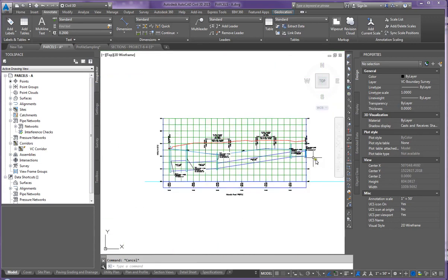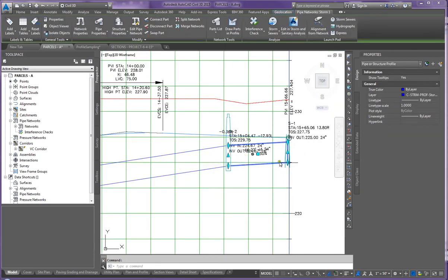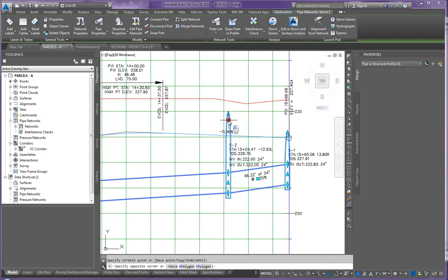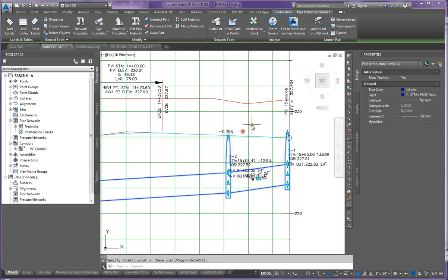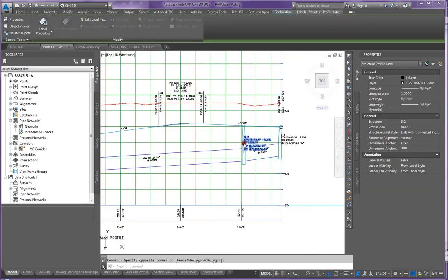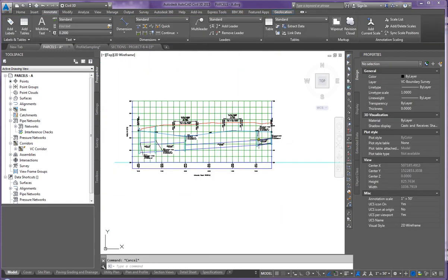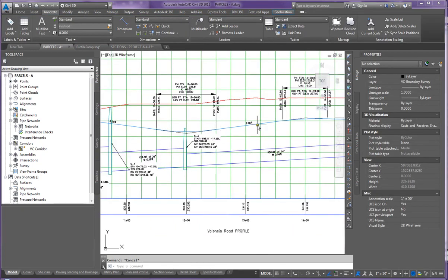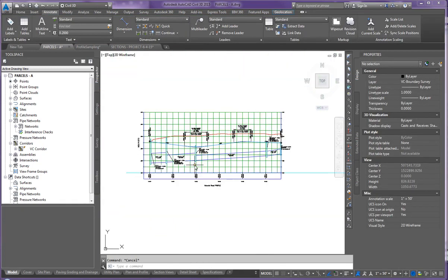All right, so you got to be careful on how your pipes look. Now this one's above grade also. So I'm going to bring this down and that down and that down. Now technically I would be doing all these calculations by hand and make sure the information was right, but I'm just showing you how to manipulate this. So we'll take a look at the data, and I'll give you the data in class on how to type what elevations all these should be. But for right now, this is basically what the storm profile would look like.